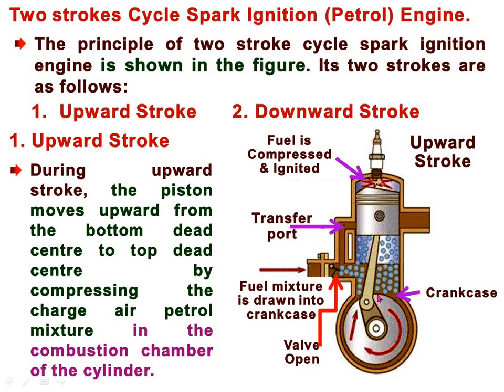This is called the inlet port. Through this opening it is transferred to the engine cylinder. This is called the transfer port. At a particular instant it opens, and fresh air fuel mixture is introduced into the cylinder.